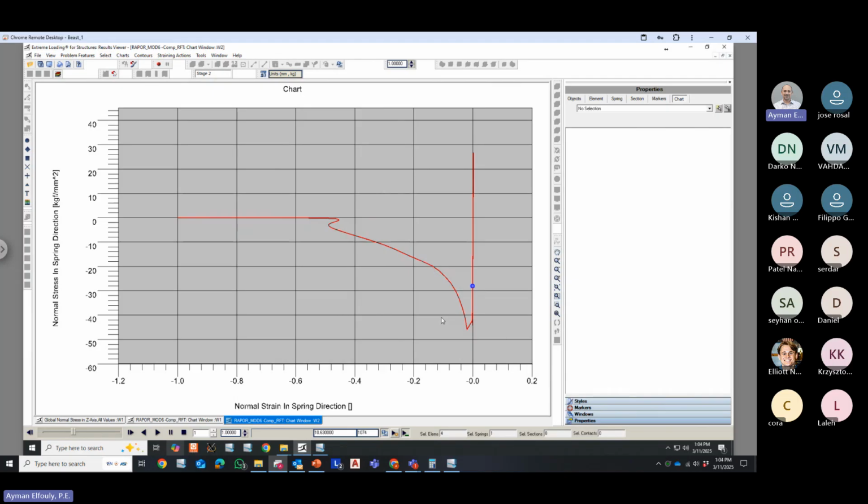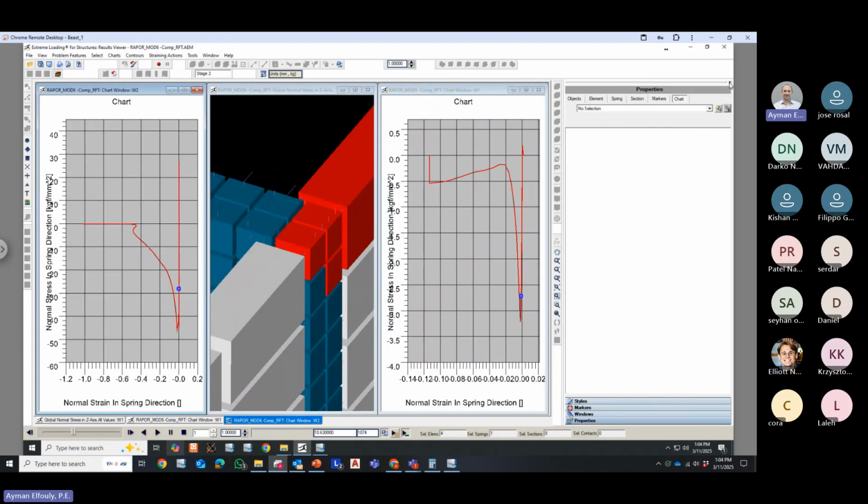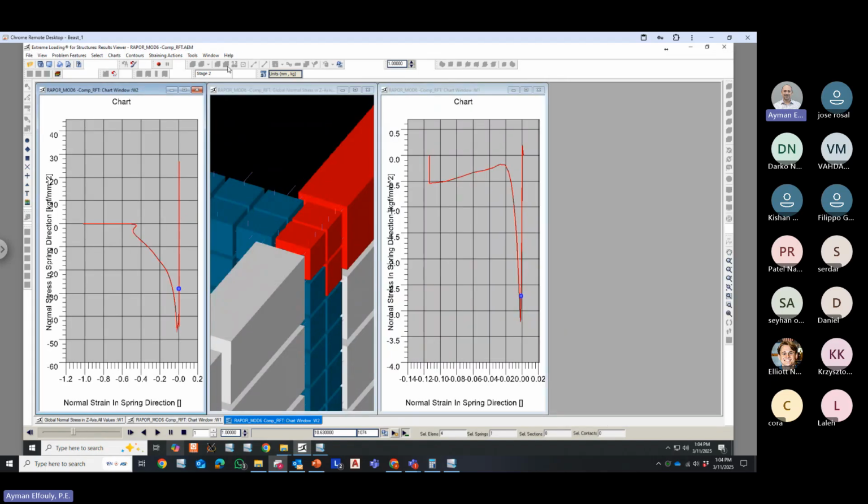We applied here a buckling model for the reinforcement rebar. When it reaches a certain strain and stress, it fails, and it applies what we call the fracture energy. Now I want to put these three pictures, or these three animations, beside each other.